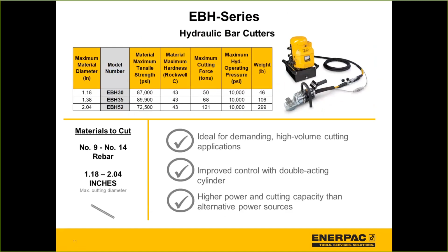Also available from Enerpac is our new line of EVH cutters. So here we have 3 sizes of hydraulic tools, and if you look at the picture to the right, you'll see that these tools are connected to the pump, and included in that connection is a twin hydraulic hose and also an electric cable. And in case you're wondering what that electric cable is doing there, it allows the user to control that tool directly from the handle. So although you are connected to an electric pump, you don't have to be going back to the pump and pushing buttons. You can control advance and retract directly from the handle of the tool, making it a very simple tool to use.